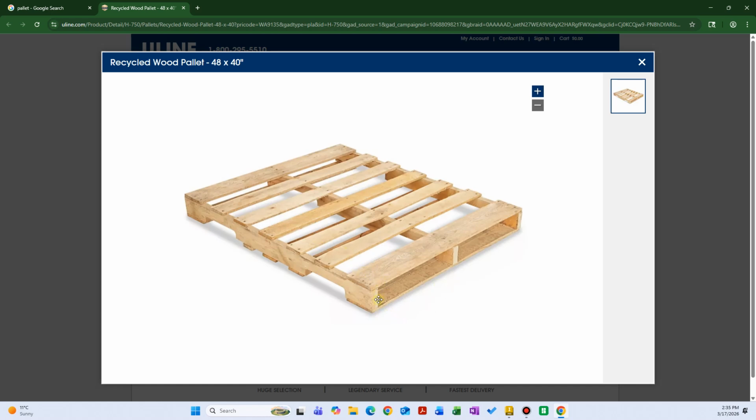So I'm assuming that this thick one is a 2 by 4, and this thin one is a 1 by 4. And we're going to create those two components and use the flush and mate constraints to basically place them in the assembly the way we want them to be placed, the way they're going to be assembled.